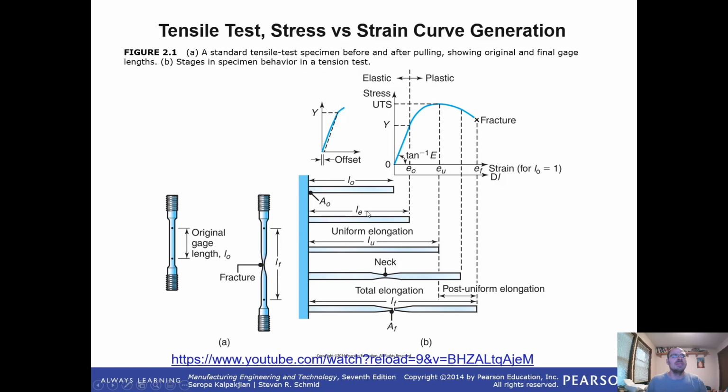What that means in most metals is, as we talked about with yield strength, and one of the questions asked in one of the quizzes was what is that, when the atoms' bonds start breaking and sliding from atom to atom, right? Well, this is called uniform elongation before that point. So before our yield point, this is a yield point here, and this is what's depicted on what's called a stress-strain curve. Before I go too much further, let me explain this curve.